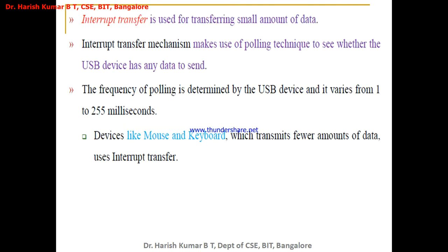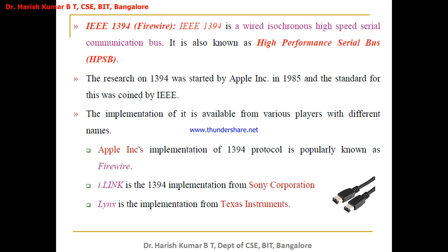Now interrupt transfer is used for transferring a very small amount of data, for example the mouse. What data do you transfer? Only a click, and for the keyboard, only a button press, so only a small amount of data is going. These days you have the USB mouse and USB keyboards, and all of them make use of interrupt transfer because only a small amount of data is being transferred.